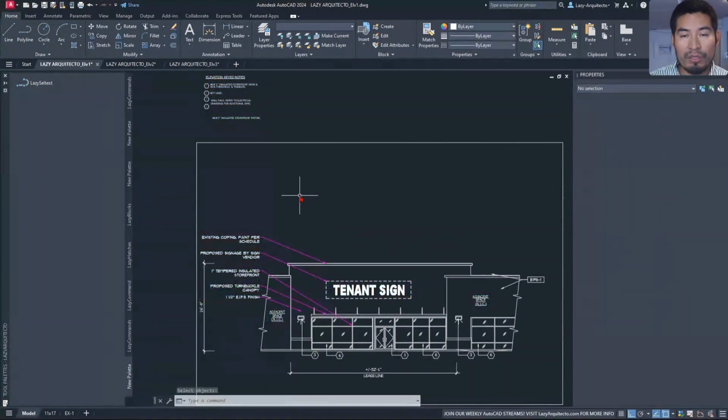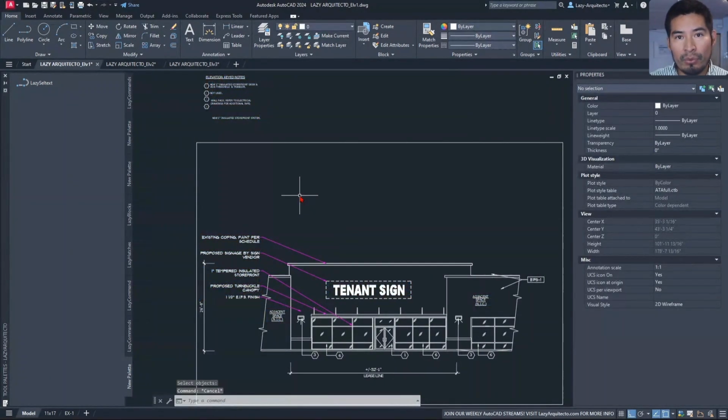For people who are new to macros, a quick explanation is that a macro is a way to run multiple commands with one single click, right? For instance, let's say when you want to clean your drawings, you always use the purge command, you always do a zoom extend in your drawing, and you always save and close your drawing.